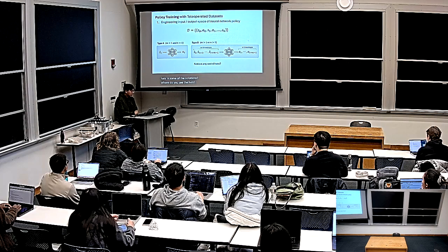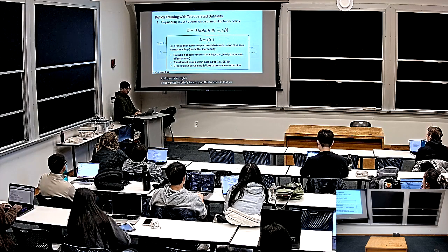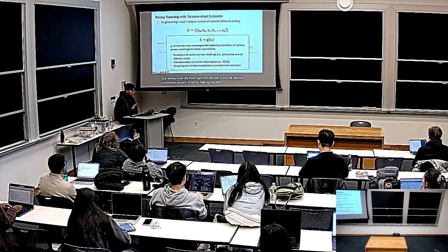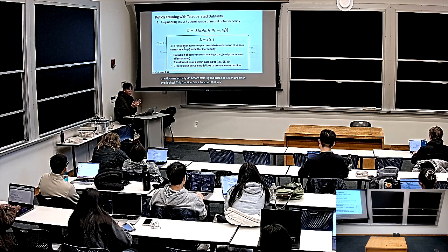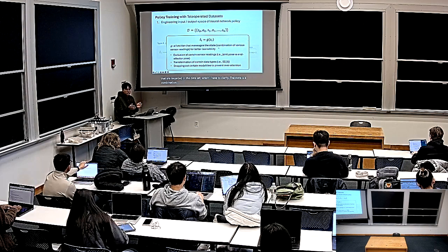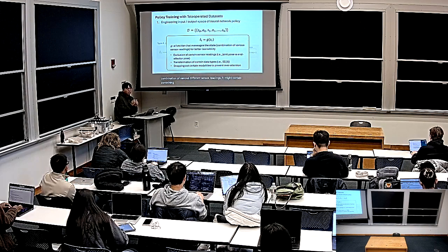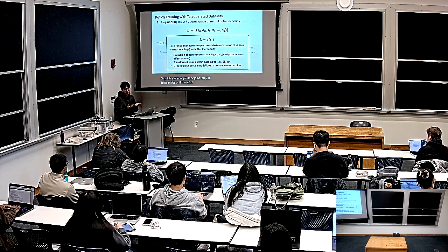On the states, right? I just wanted to briefly touch upon this function G that we robotics practitioners do before training on the data sets, which is often overlooked. This function G transforms the states that are recorded in the data set. The state is a combination of various different sensor readings. It might contain camera feeds, joint states, joint torques, joint angles, or if the robot has tactile sensors, tactile readings can be included in the states as well.